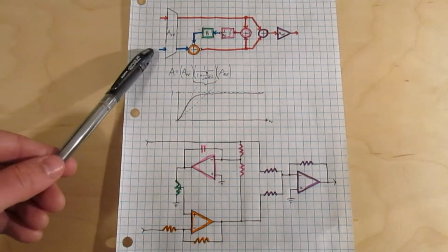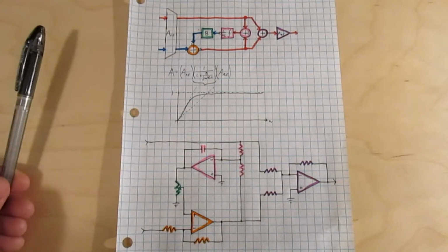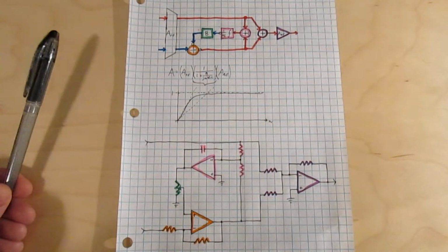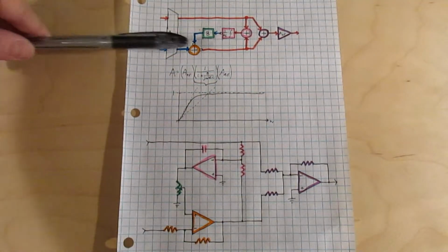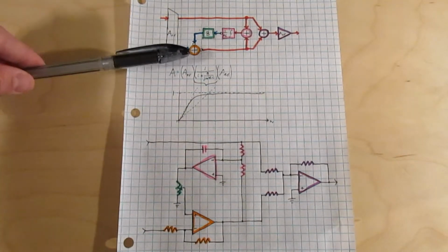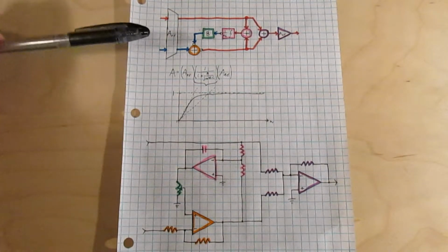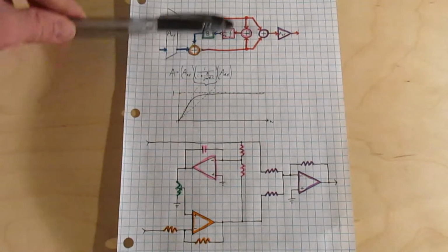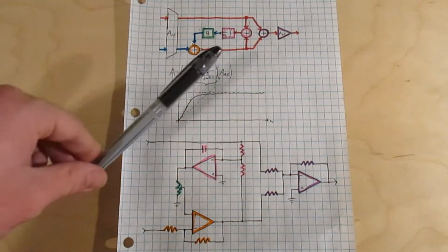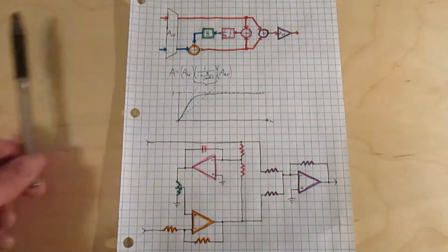This means that any DC offset we have at the input is going to get tracked out at about half the speed as it otherwise would be. So if there's a DC offset at the input, it will still eventually get tracked out, but because it tracks more slowly, it won't be able to react fast enough to cancel out a low frequency signal coming into the input. And that's basically what it means to have a lower corner frequency on this filter.